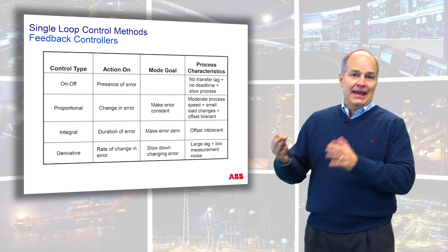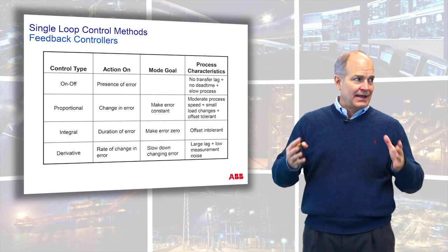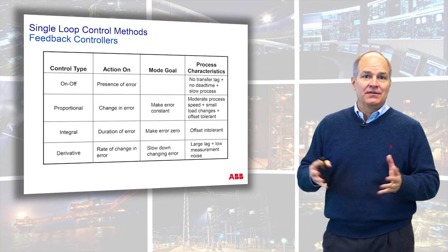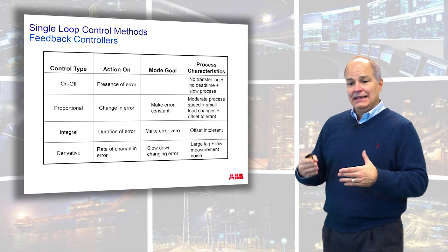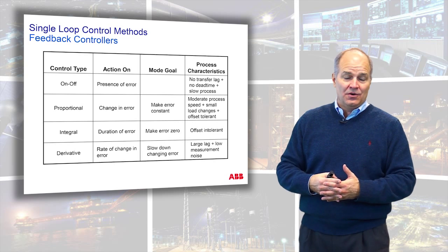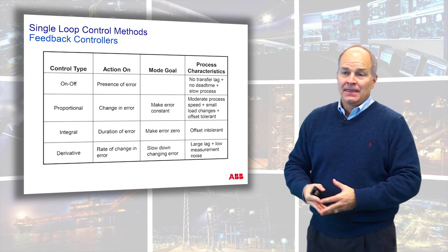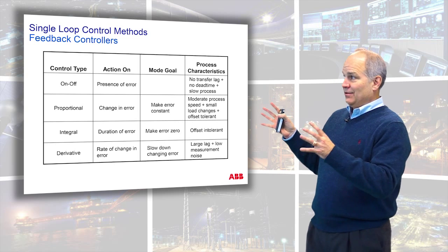Derivative is really an enhancement to the PI algorithm, so you would very rarely, I can't think of an instance where you would ever use derivative by itself, but it's a lead action to try to anticipate where the process is going and make a correction before the error gets out of hand. That is, in general,